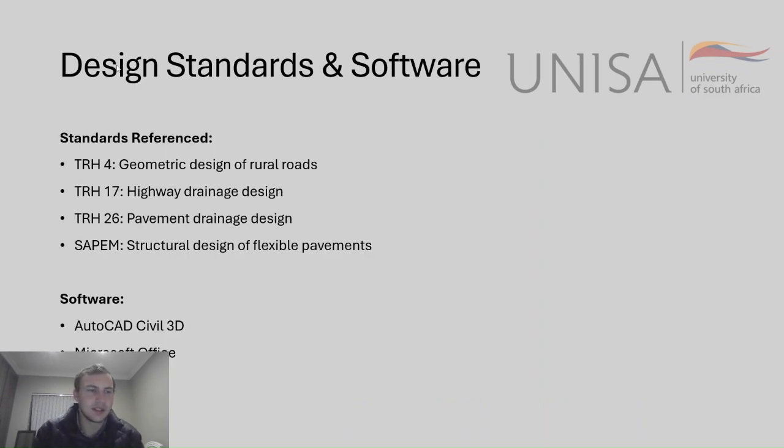The design standards and software. The design standards that I've used are the TRH4, geometric design of rural roads, TRH17, highway drainage design, TRH26, the pavement drainage design, and the SAPEM, the structural design of flexible pavements.